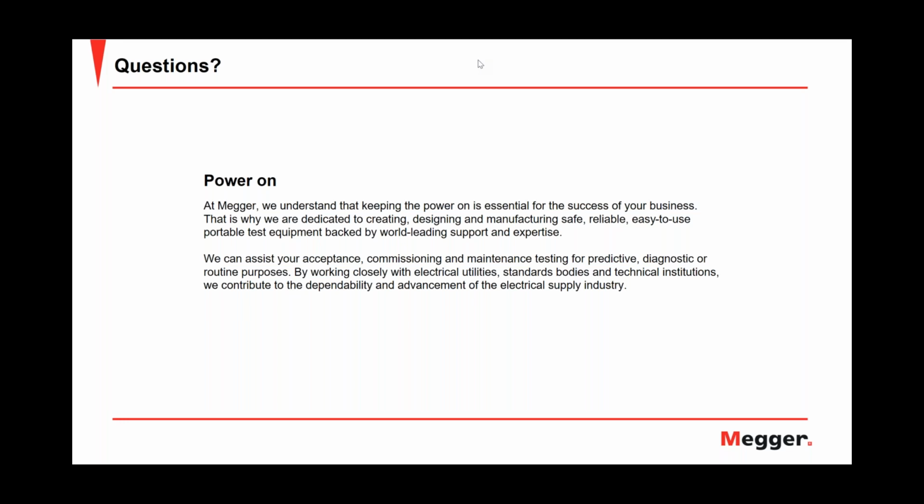That's one thing. So the chances of really hurting the insulation are pretty much not there, because a lot of people ask this question. They know now from the cable testing world that solid dielectric cable should never be subjected to DC testing anymore, because you will damage the insulation. However, that is a different test. That is a pressure test, 30 minutes or longer at substantial overvoltage.